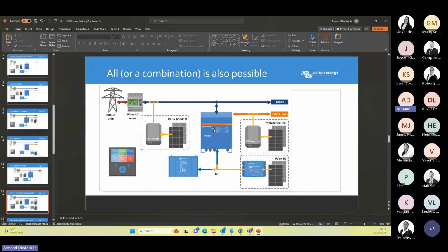For argument's sake, once your power produces 80 kilowatts, and all of a sudden the consumption goes from 80 to 0 or 80 to 10, that 70 kilowatt needs to go somewhere, and it needs to either go to the batteries or go to the load. And if it can't go somewhere, it will blow up the transformer on the Victron inverter as such.